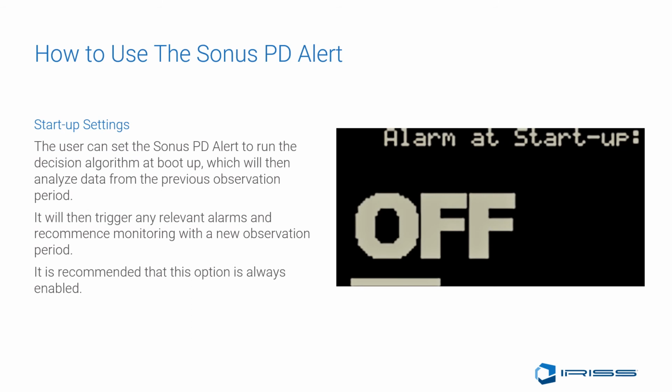Startup settings. The user can set the Sonus PD Alert to run the decision algorithm at boot up, which will then analyze data from the previous observation periods. It will then trigger any relevant alarms and recommence monitoring with a new observation period. It is recommended that this option is always enabled.